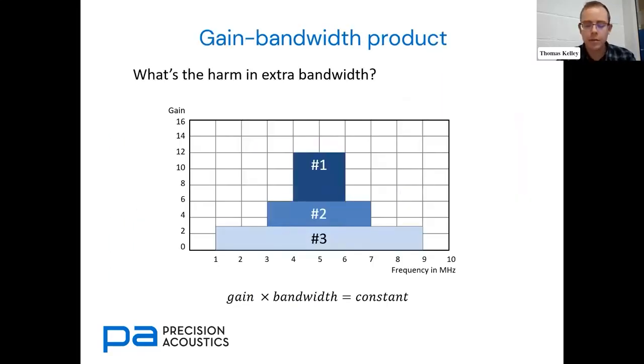In a very brief summary, transducers with a high bandwidth will typically produce a lower output than transducers with low bandwidth. So high gain, low bandwidth, or high bandwidth, low gain. You can almost approximate it as gain times bandwidth being a bit of a constant. Obviously, there are things you can do to swing it around a bit, but as a general concept, that holds very well.